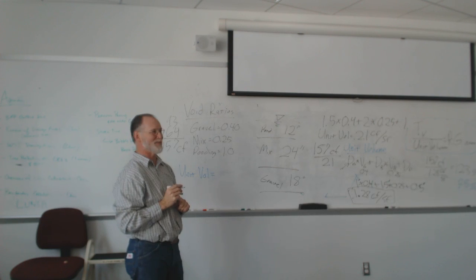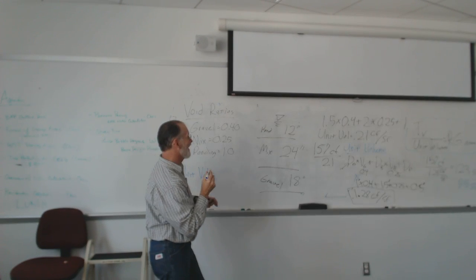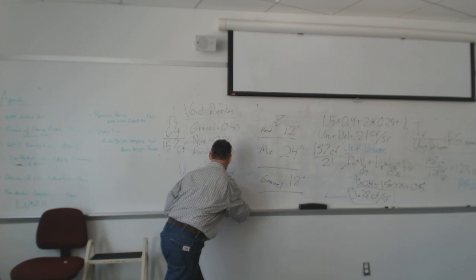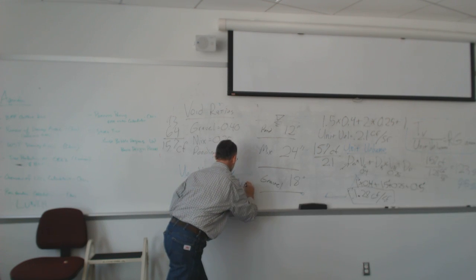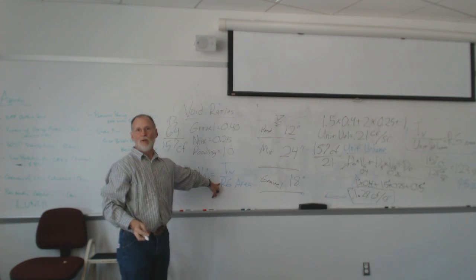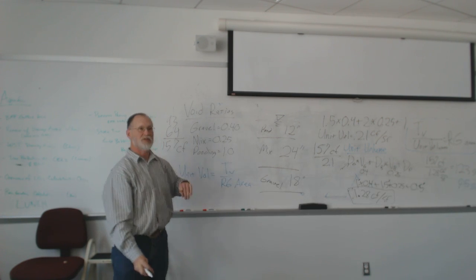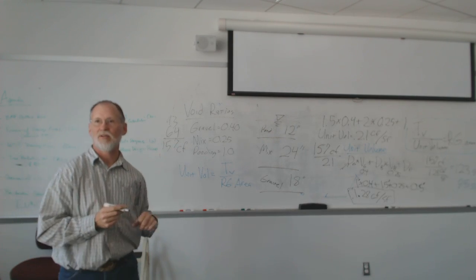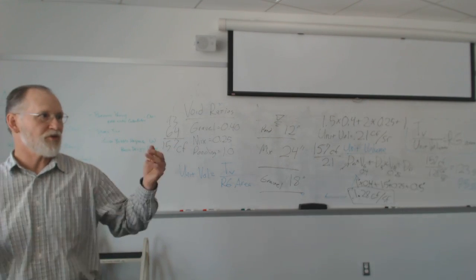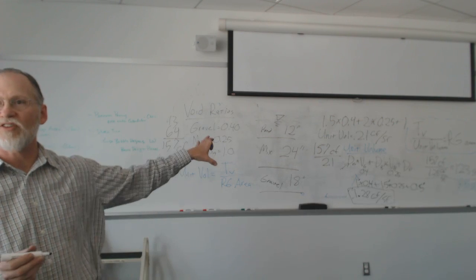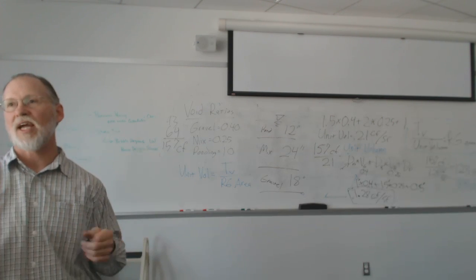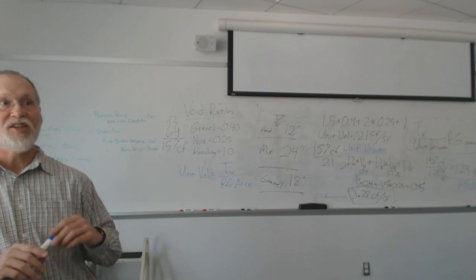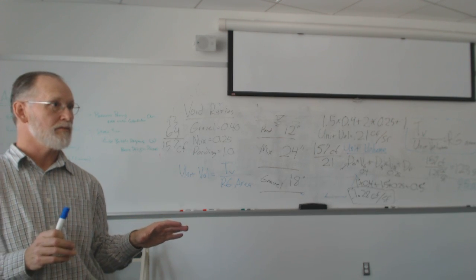Who remembers 9th grade algebra? Nobody? Treatment volume divided by the rain garden area. So if I want a 100 square foot area and I know my treatment volume, I can work out my unit volume, and then play with these ratios in a spreadsheet to optimize, or at least check your numbers to make sure they meet that. Nothing wrong with going bigger.